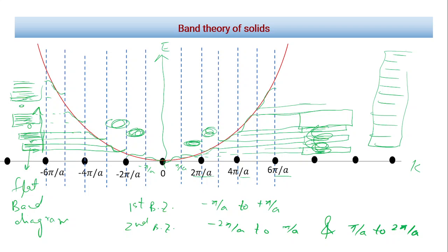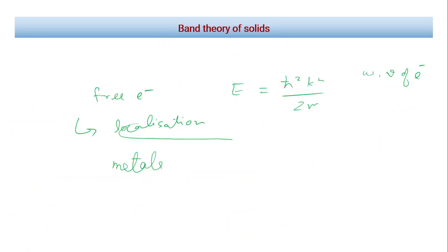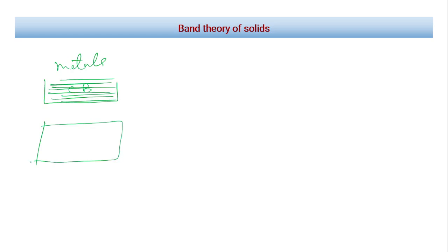and this is how we get energy bands in our solids, and here we specifically were seeing for metals. So this is how we define metals, that in metals, when we say we have conduction band, that is actually a bunch of lot of energy levels very closely spaced, and then we have another which we call valence band.